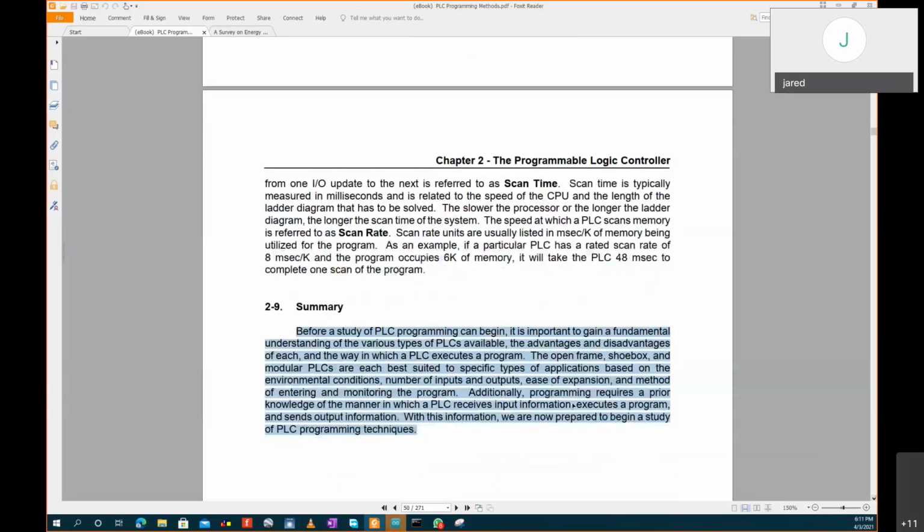So now that I've told you how a PLC works, what do you mean by a scan cycle, what do you mean by a program logic, what do you mean by input, what do you mean by the update period, the startup period, the loading period, the run time. So those are some of the things that I've discussed today. And now you understand when a PLC is in on mode, run mode, jog mode, off mode, what does it mean? When the PLC is doing a scan, what is it really doing? When it's doing an IO update, what is it really doing? When it's solving the ladder, what happens then? How much time does it take for the PLC to do a scan and be able to execute the ladder?